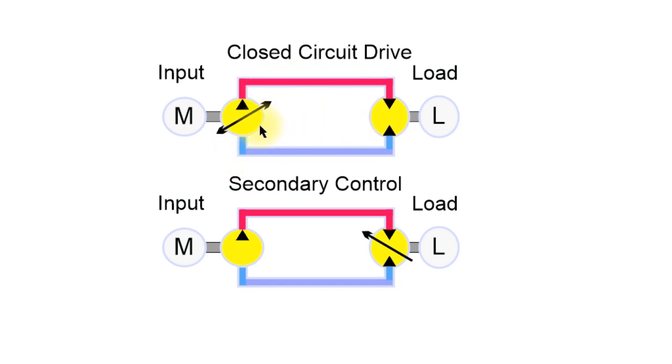This is very simplified, but this gives us the facility of running in both directions, so both lines can be pressure lines. You can take the pump through over 180 degrees and run the motors forwards or backwards. Nice efficient system, no control valves needed on this one, because we've got a good hydraulic stiffness in the two lines.